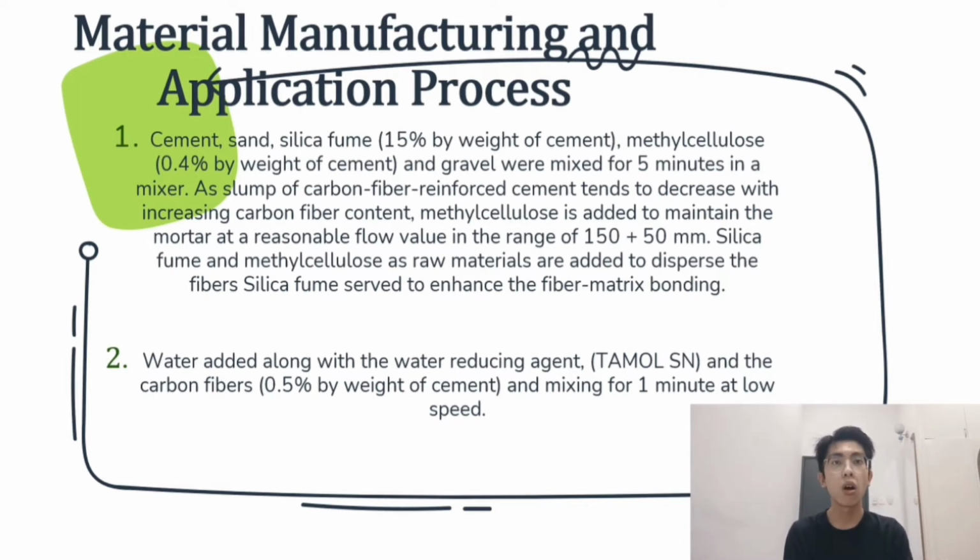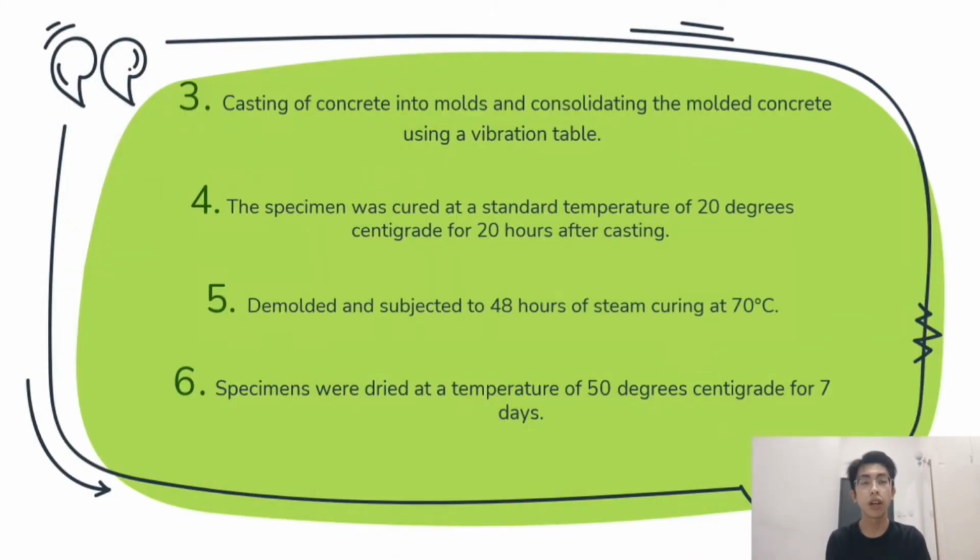So second, water along with the water reducing agent, which is Tamol SN, and the carbon fiber, which is 0.5% by the weight of cement, and mix for 1 minute at low speed, casting the concrete into mold and consolidating the molded concrete using a vibration table.